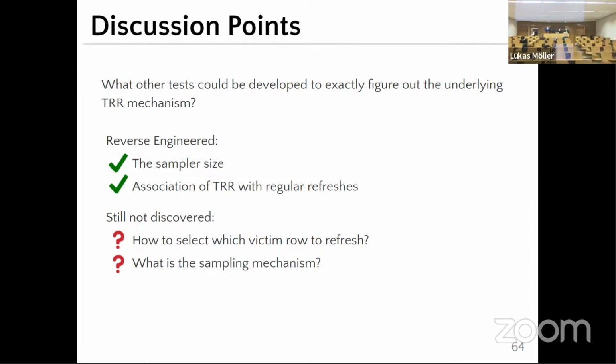So I don't fully, again, maybe I missed this, but when the PTRR mechanism refreshes, does it refresh one victim row, or does it refresh a bunch of victim rows in the blast radius? Okay, so the paper says, and it's also something I think is a weakness of the paper, the paper says as an observation that it doesn't say for the PTRR, but it says for the in-DRAM TRR that it just refreshes a single victim row.